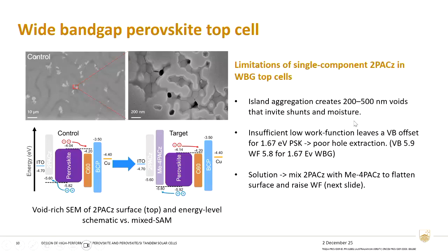Also, the energy level of some of the widely used SAMs, here 2PACz, as I mentioned earlier, doesn't have perfect or ideal energy level alignment with the perovskite, particularly for the wide-bandgap perovskite, where the energy levels shift compared to the lower bandgap perovskite. For example, the valence band goes deeper compared to the lower bandgap.